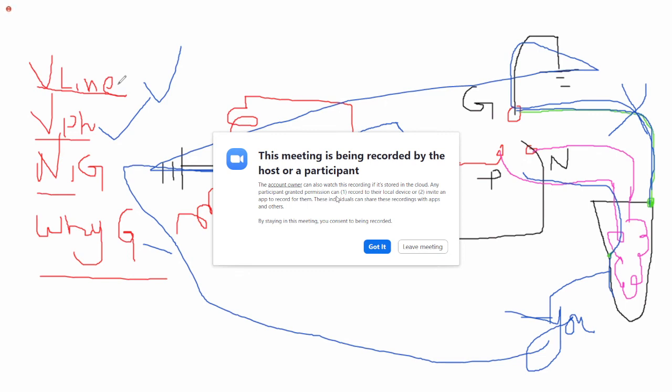Why ground? Safety. Basically you will get a shock, but it will trip. With grounding, a shock will occur, but the person is affected only for the duration, and the moment you got electrocuted, immediately the breaker will trip. You get a shock in the cabin because the neutral is grounded and your feet are on the neutral. The moment you touch a phase, you start shivering, but the breaker trips. Now you understood why you get shock, because you are already sitting on the neutral node.